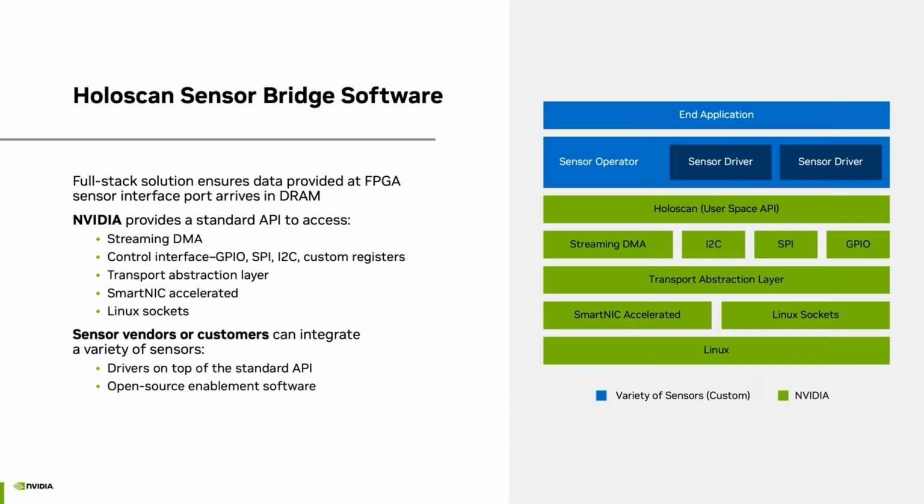The key thing about the sensor bridge from a software perspective is streaming DMA, the ability to easily access control interfaces like GPIO, I2C, SPI, things like that, the transport abstraction layer, and also the ability to access the Linux sockets. We're working with a number of sensor vendors to integrate the sensor bridge directly into the sensor. So depending on what type of sensor you're looking for to integrate into your application, you will also be able to leverage that.